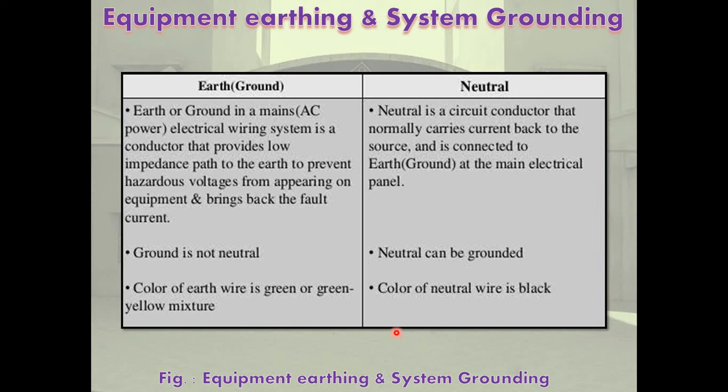An earth fault relay in the neutral CT can trip the circuit breaker. Earth fault can be easily sensed. Without neutral earthing, earth fault protection becomes practically impossible. Next, arcing grounds due to repeated charging and discharging of the phase to ground capacitors through a minor earth fault anywhere on that voltage level are eliminated or minimized by neutral earthing at that voltage level.